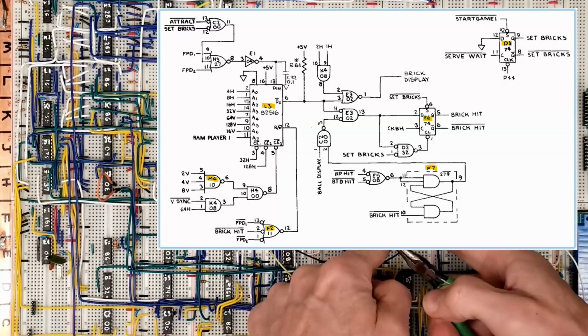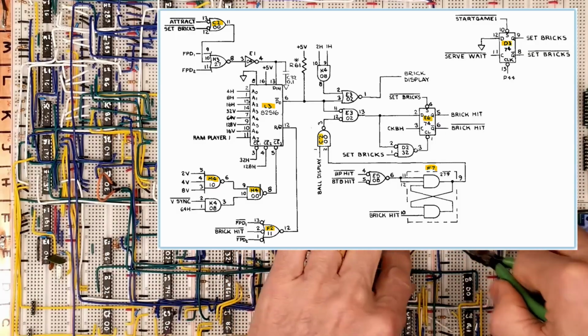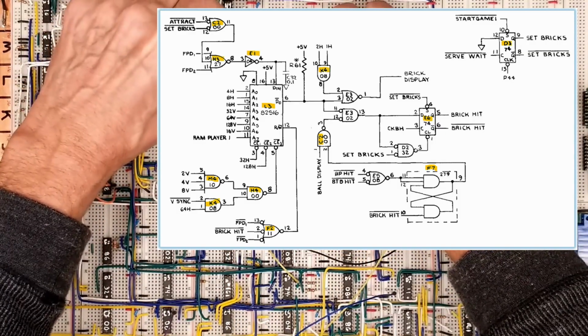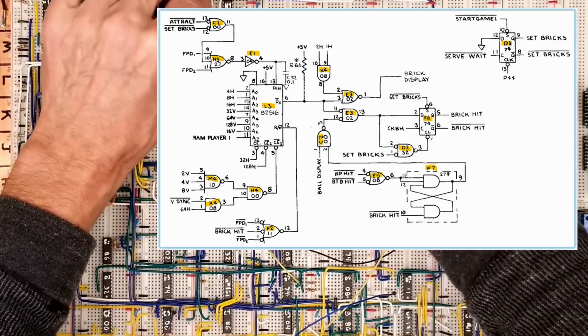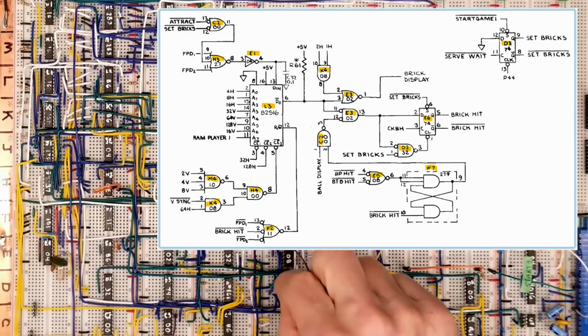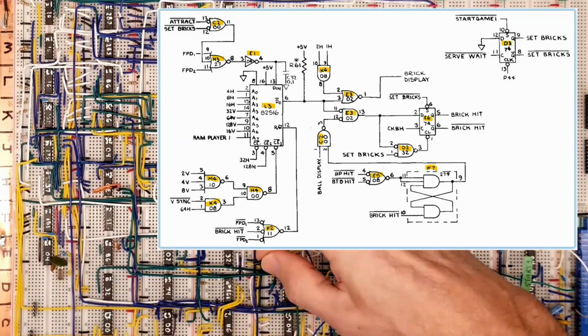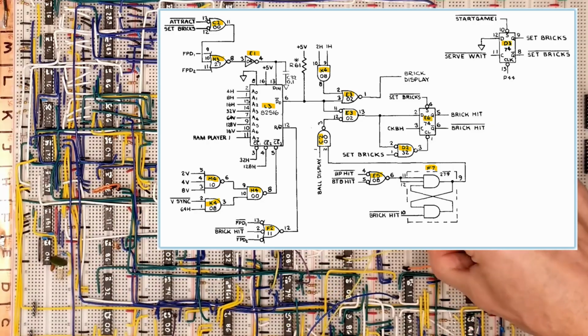We'll also use a wide variety of existing gates from Charlie 2, Henry 4, Henry 3, EZ1, King 4, EZ5, EZ3, and Dog 2. This is a smaller section of the schematic, but there's a lot of nets to wire up here. I think over 50. To save some time, I'll just use jumpers for now and hardwire this afterwards.